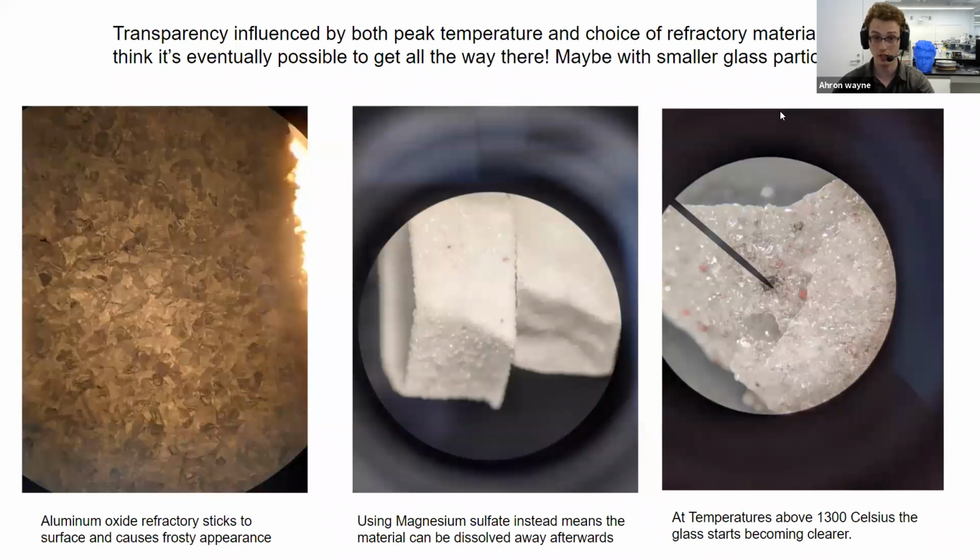It's clearly not transparent. Most of the reason for that is because of the presence of air or porosity in the part. But part of the reason is also that the refractory material, the stuff I pack it in the crucible, it's an oxide and it sticks to the glass at high temperatures. So here under a microscope, we can see these sharp shards